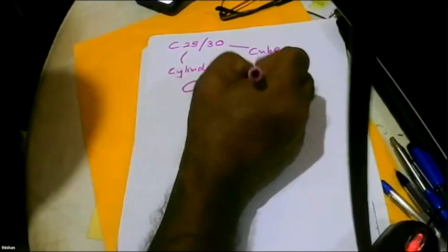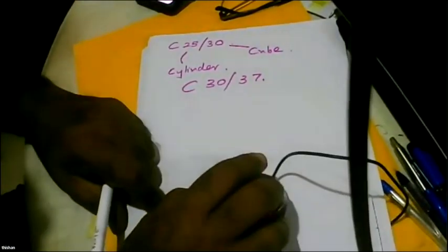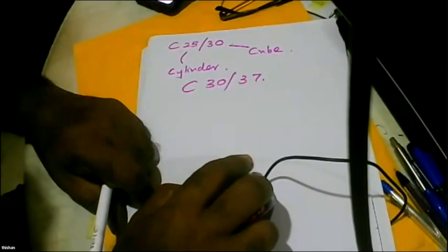So I will start with the DE story, that is, how to make a mix design. When we are using Eurocode, we have C25/30. C25 is the cylinder strength, and the second is the cube strength. We also have C30/37, and we have many others. Last time I showed you the type of things we have, and I can share the screen.